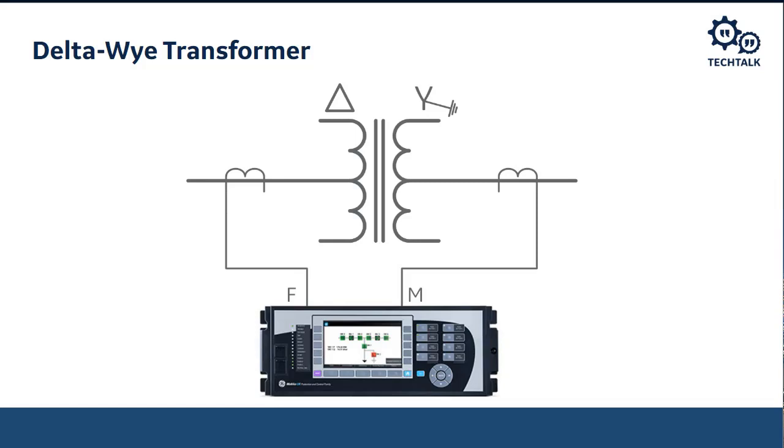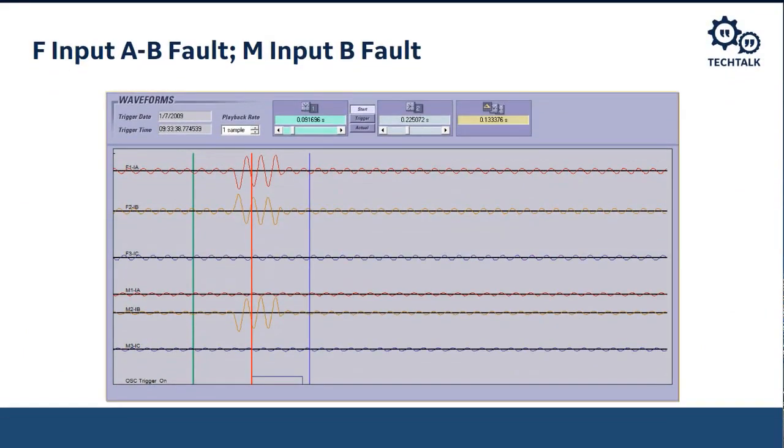So that'll be important. Now, the interesting thing about this particular fault that we're going to look at is that the fault is where we expect it to be. It's out on the distribution system. So it's a temporary fault, and it's out on the distribution system. It might be a squirrel that got electrocuted and fell off. It might be a tree strike, but it looks like it's a fault that lasts 1, 2, 3 power system cycles.